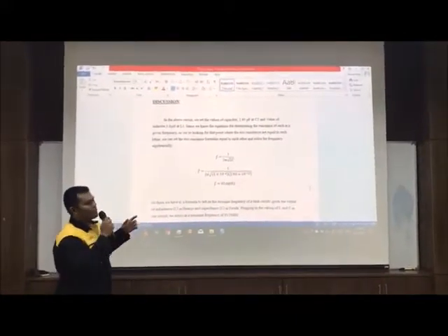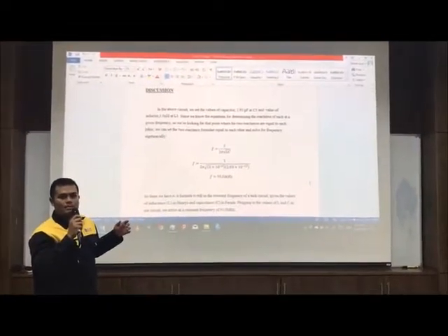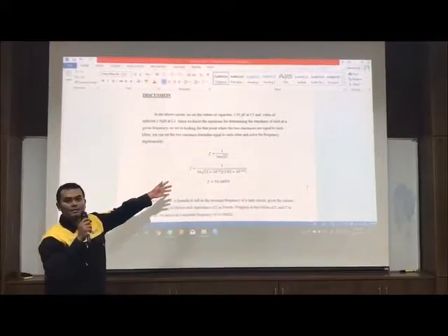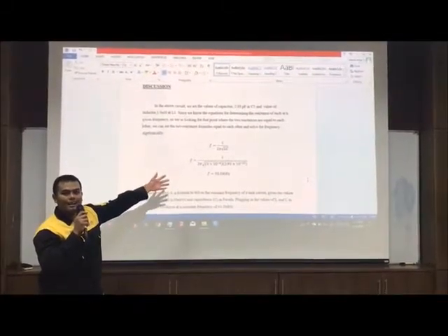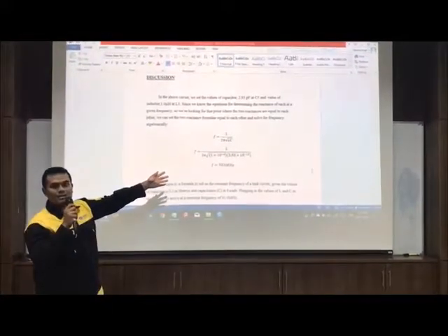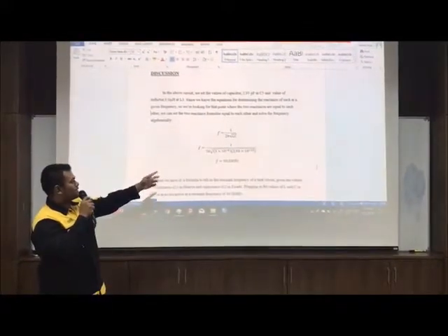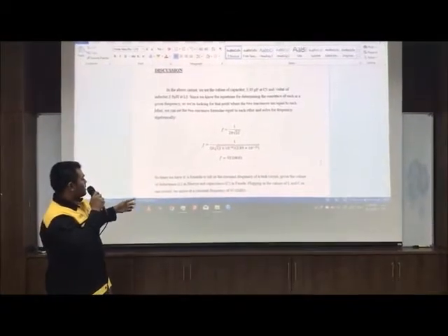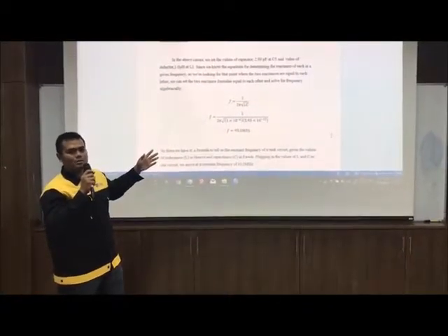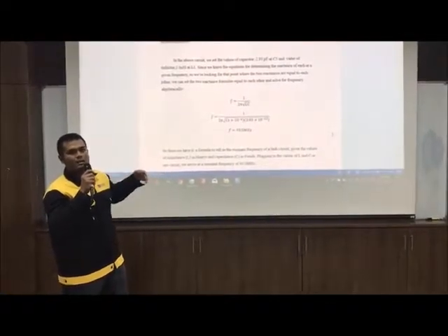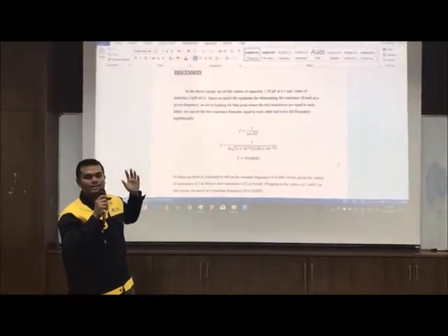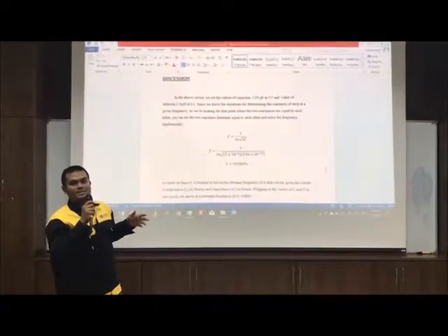Then if we want to find the frequency of our FM receiver, we can put these into the formula. We calculate, and we get our frequency of 93 megahertz. By this formula we can also get another frequency by only tuning the variable capacitor and the inductor. So thank you.